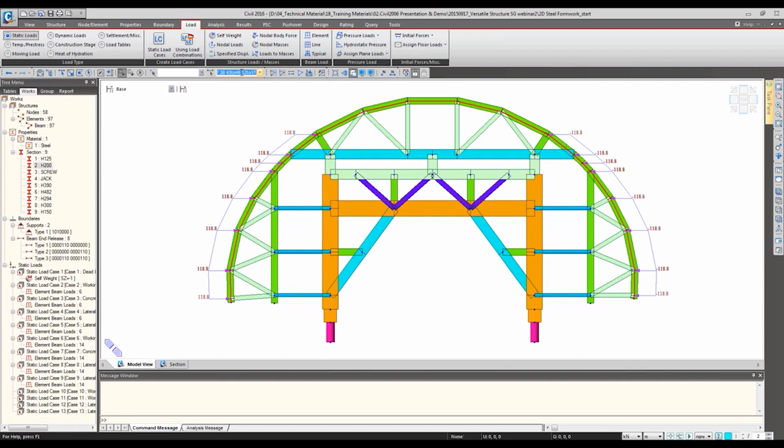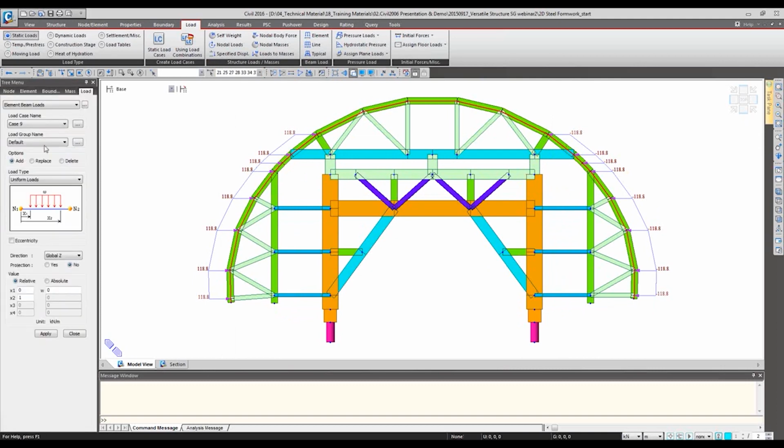So I selected this part, and then we are going to enter the vertical load for the vibration and the impact, the same value as the previous stage. And next, the dead loads for the concrete, and likewise in the vertical direction. At this time, the lateral load.